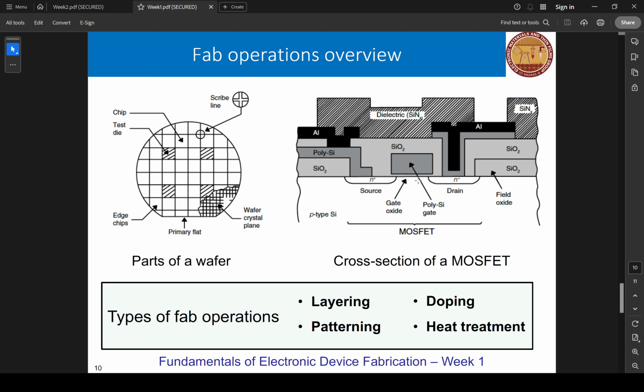But in 2D material, since it's a limited thickness, 1 or 2 nanometers, by giving a small voltage only, you can completely deplete the carriers from the material. So that way it won't conduct at all. So it's a different concept. It works on a slightly different concept than silicon.